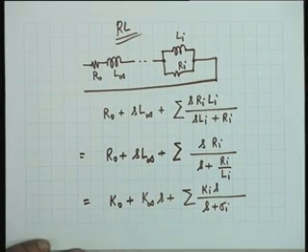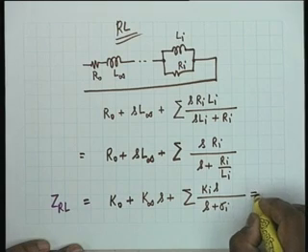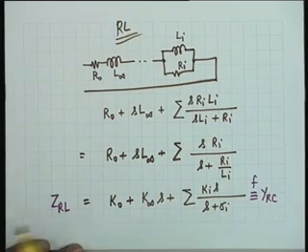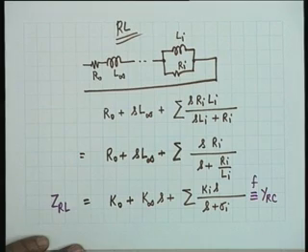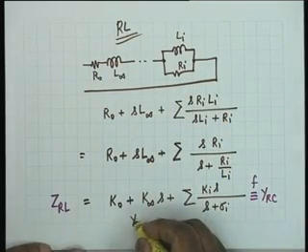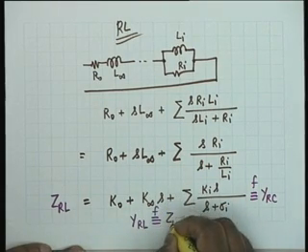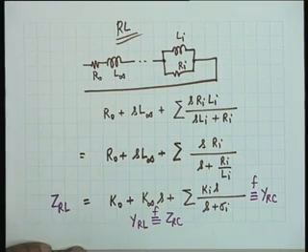And if you pause for a minute, you notice that this is exactly the same form as YRC, and therefore whatever we have said about YRC is applicable to an RL impedance. For example, if you want to expand an RL impedance in Foster 1, you have to first divide by S. All that we have said about YRC now applies to ZRL, and by the same token YRL shall be of the same form as ZRC. Just take the reciprocal of both sides.